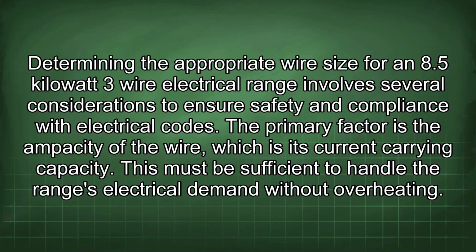Determining the appropriate wire size for an 8.5 kilowatt 3-wire electrical range involves several considerations to ensure safety and compliance with electrical codes. The primary factor is the ampacity of the wire, which is its current carrying capacity. This must be sufficient to handle the range's electrical demand without overheating.